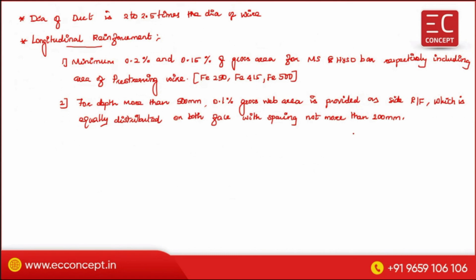So that means this, as a side reinforcement, which is equally distributed on both sides. Okay, this side and this side, and the spacing should not be more than 200 mm. So this is very important.